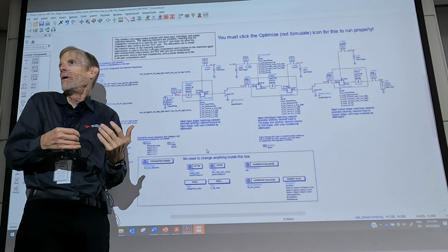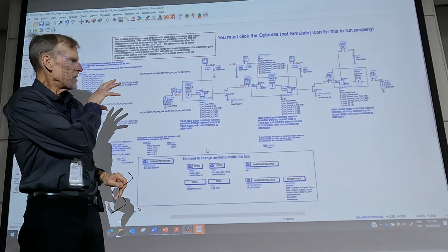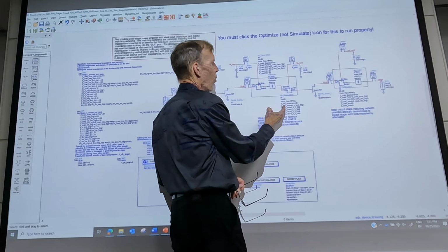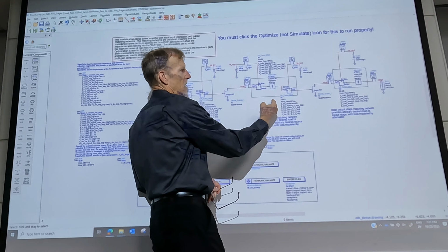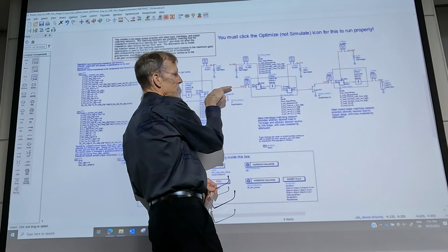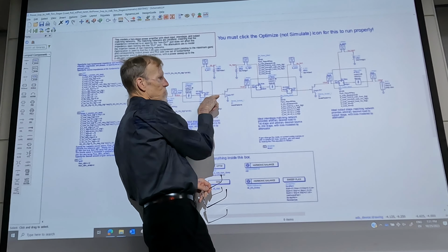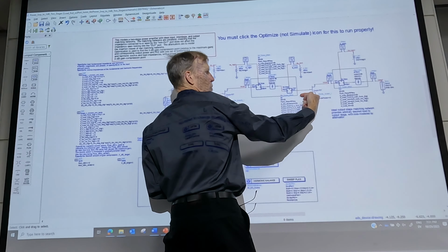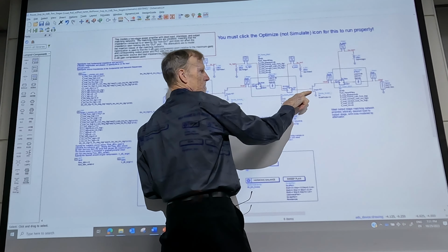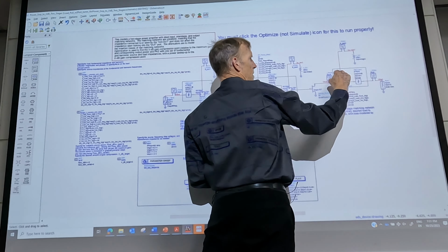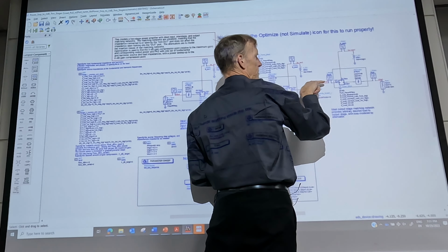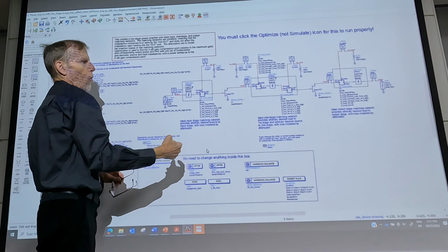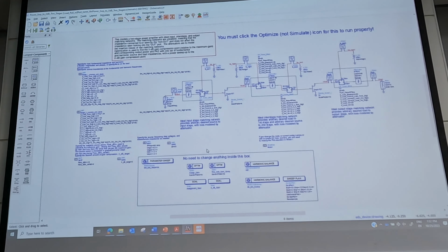It's a model. So what this simulation does is, if you could come up with an interstage network that presents the ideal load that this stage wants to see and simultaneously presents the ideal source impedance that this stage wants to see, and you also have another network that presents the optimal load and similarly the optimal source for the input, what's the performance you would get from it?